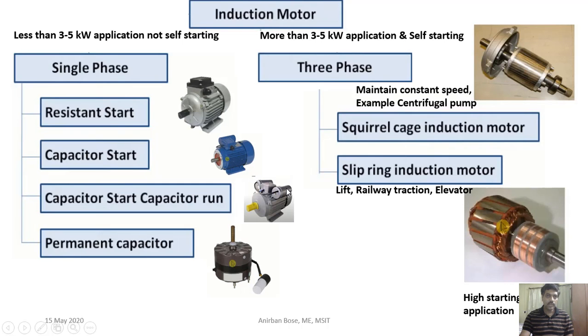Okay, here you can see single phase, if it is less than 3 to 5 kilowatt application and not self starting. So single phase induction motors again can be resistance start. I have told you already, single phase induction motors are not self starting. That is why some starting elements are required, like resistance start, capacitor start, or capacitor start, capacitor run, or a